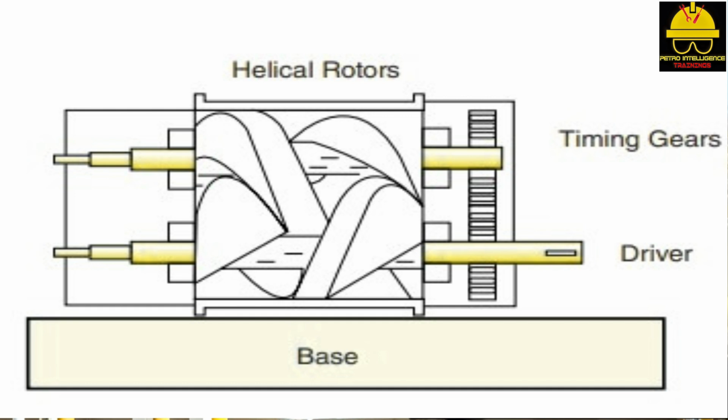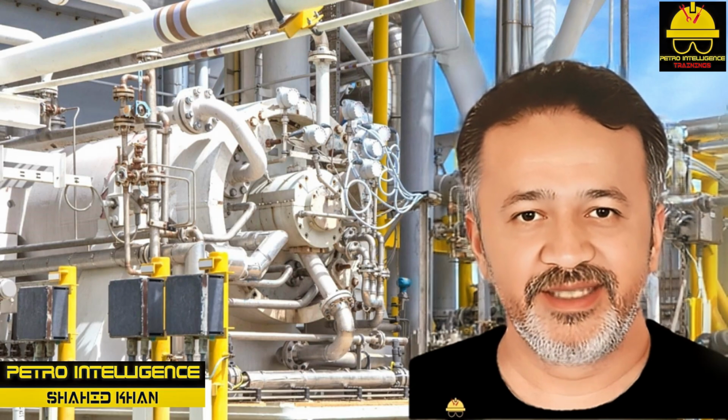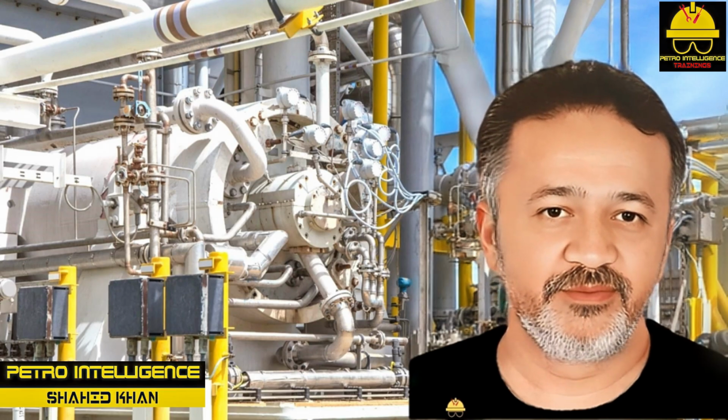Rotary screw compressors operate at speeds between 1,750 and 3,600 rpm and have capacity ratings above 12,000 cfm, cubic feet per minute, on the inlet volume and discharge pressures between 3 and 20 psig. Some rotary screw units can operate between 60 and 100 psig.